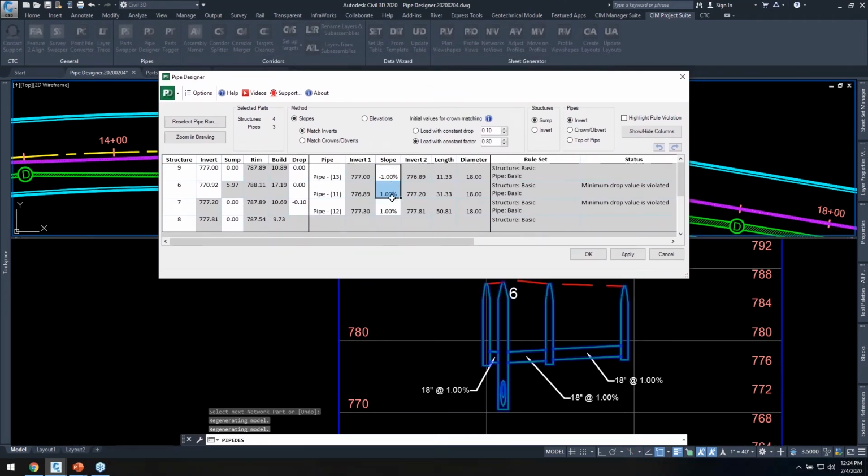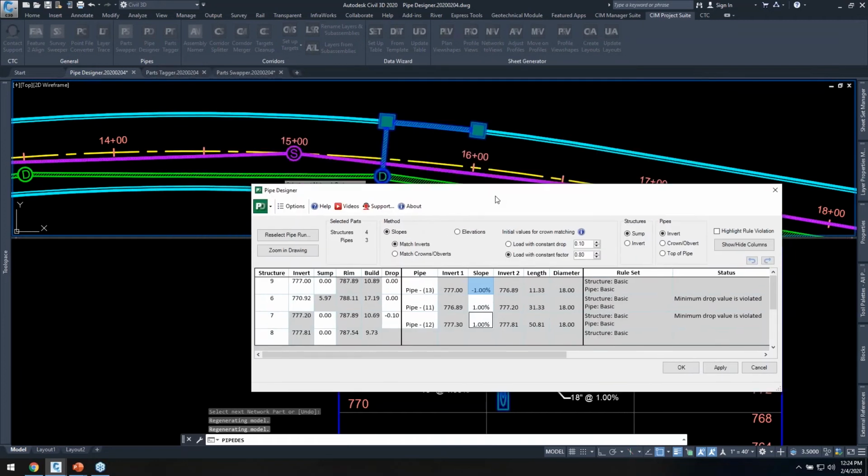Different ways where we can auto-calculate slopes, perhaps holding a constant pipe cover, or maybe say grab this structure or this pipe and calculate the slope by holding the starting and ending inverts, interpolate the slope basically across that whole thing, or assign slopes from the rule sets. A few other little handy tools we're going to add to it, but right now it's got a lot of features in it, and like I said, it's probably one of the most popular tools.